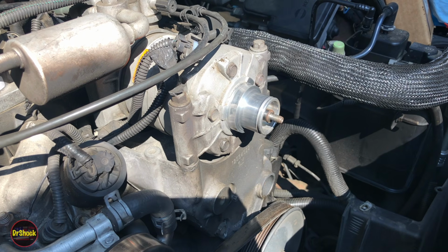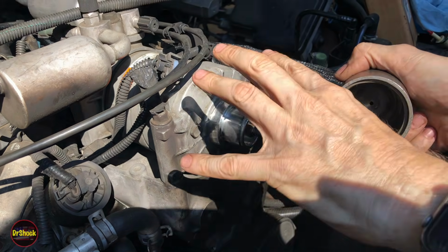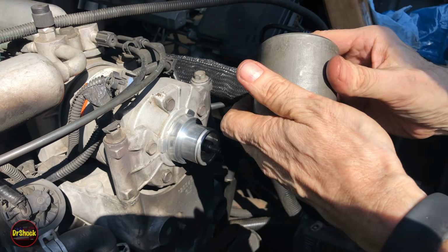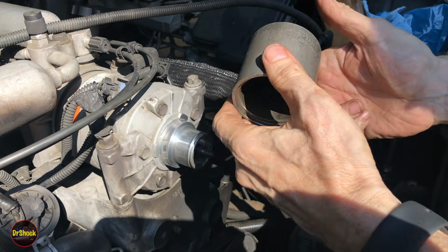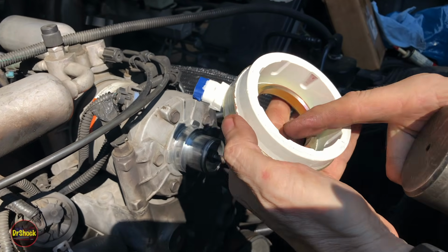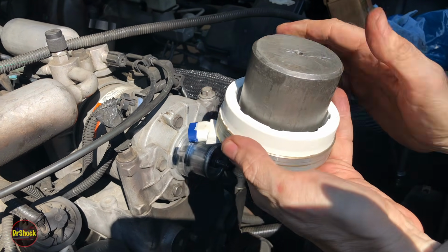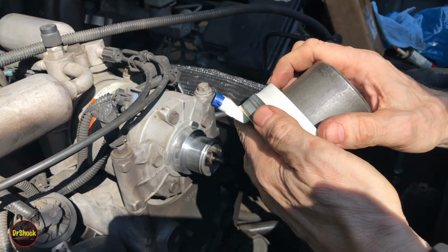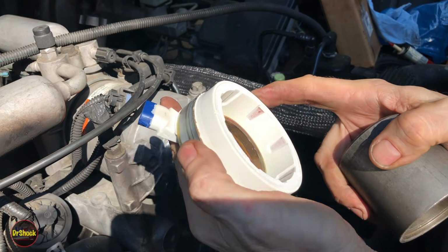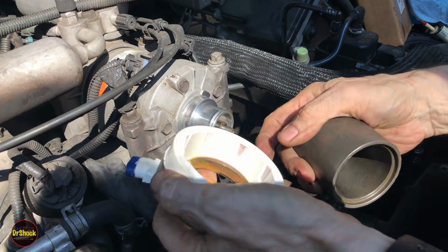Now to put this guy back on, normally the way GM would want you to do it is it'd be on the press, and you'd use this tool. There's a bunch of different manufacturers. Again, like all the other tools, I'll put several different brands you can choose, and it's got a little groove cut in it. You can see there's a raised point on this piece here, and this guy just fits in like that. And again, it's to let you drive it on without damaging this white thermoplastic type material that runs all the way down the inside, and also without hitting the shaft.